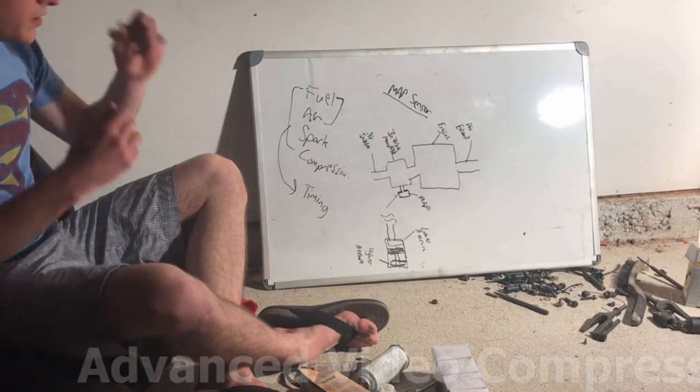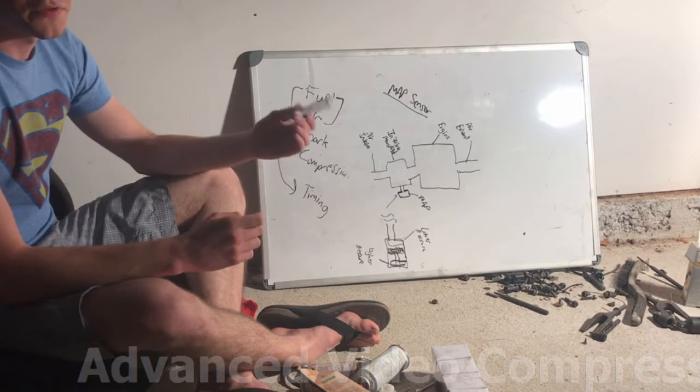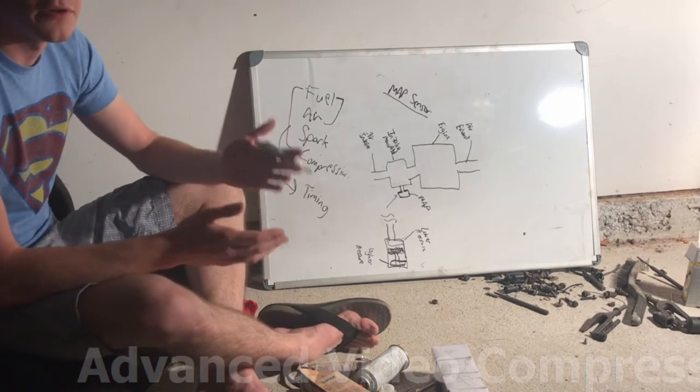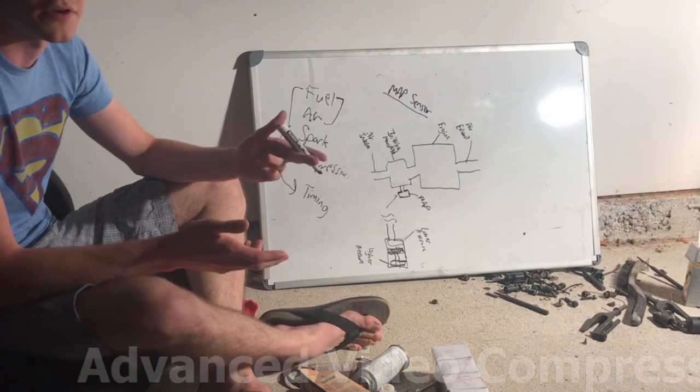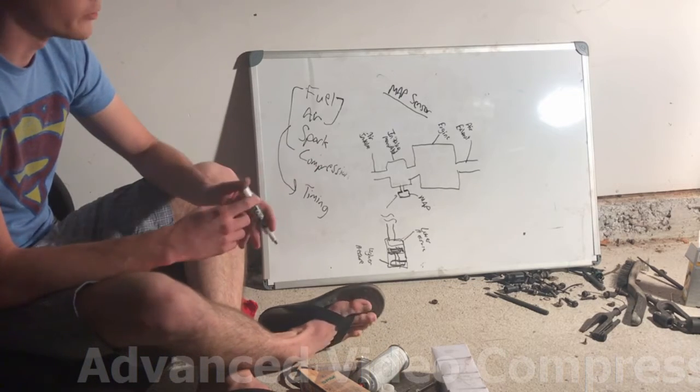And this is key because you really need both sensors, right? A MAP sensor is going to measure pressure, but in order to fine-tune airflow calculations, you really need a MAF sensor in conjunction with a MAP sensor to run the car properly. Because as cars age, they develop problems.